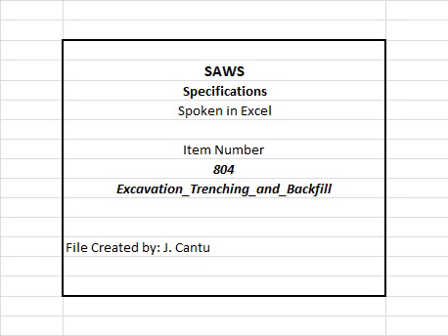B. Where copper or HDPE services, 3/4, 2, are installed, initial backfill shall be sand conforming to the following requirements. 1. Natural sand or sand produced from crushed gravel or crushed rock maximum 1/4 inch free from clay and organic material conforming to the requirements of Table 4 unless modified by the engineer. 2. Larger services utilizing DIP pipe or PVC, C900, pipe shall be backfilled the same as mains and conform to the requirements of Table 3 unless modified by the engineer in writing.